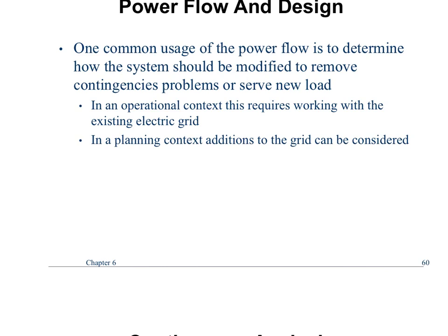So you can operate for 30 minutes under emergency conditions, which means the grid is not in a great place, but it's maintained stability. But you only have 30 minutes to get back to the place where you can take another hit on your system. You can lose the next worst case scenario. And so what contingency analysis does is look not only at that first one, but also at that second one and beyond. And so where do you put a wind farm, right? How a wind farm gets integrated into the system and how its power moves can dramatically affect the reliability of a system. So upgrades to the system.